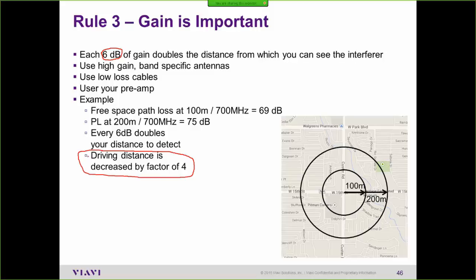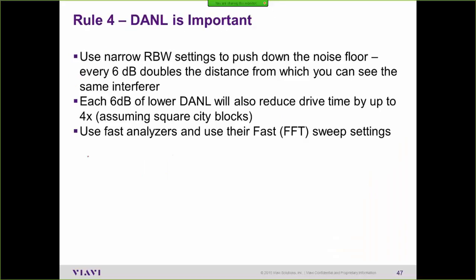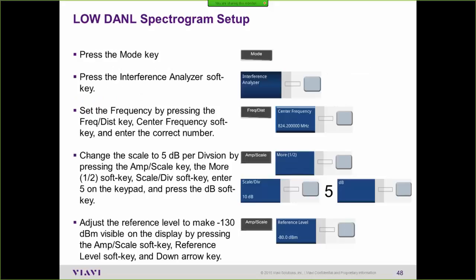We don't have time to go through it in gory detail, but you can use this slide to help you calculate path loss estimates back to the base station. Essentially, you're going to measure a power in the analyzer. If you're looking at some interference with a directional antenna pointing at it, you can see where the line is. You can estimate that the line's at about -85 dBm. So that's the starting point on the analyzer.